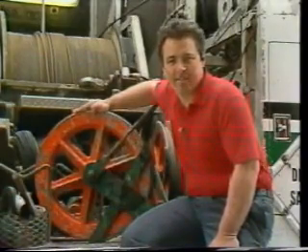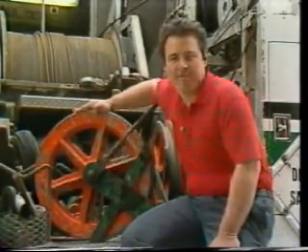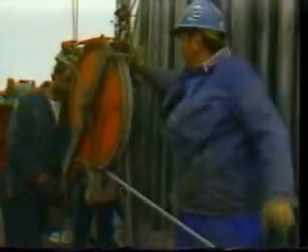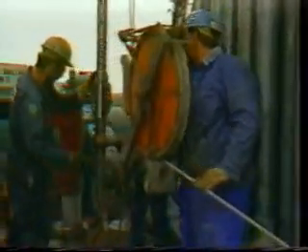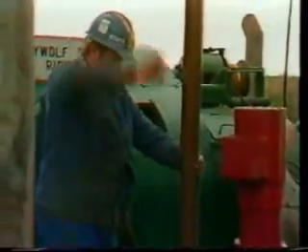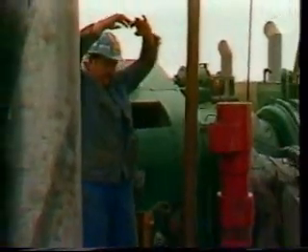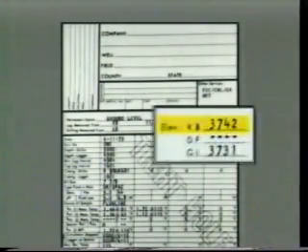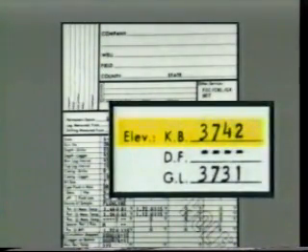Care should always be taken to see that they are well secured. Final steps in rigging up can now begin. The tool string is raised in the derrick and suspended over the hole. At this point, the well's depth reference, or 0 point, is set into the cable depth measurement systems. As noted in log headings, this reference point is usually the Kelly bushing, but may be the derrick floor or any point selected by the oil company representative. You'll learn more about this and other log heading information in GL 402.